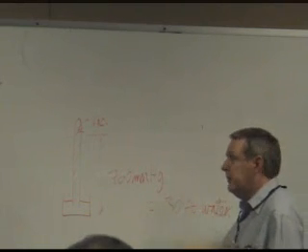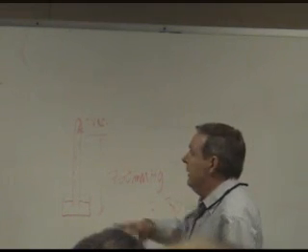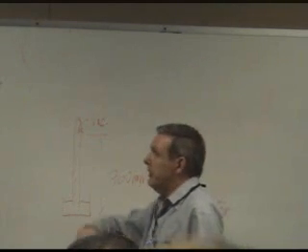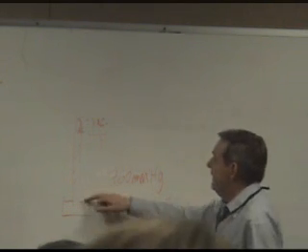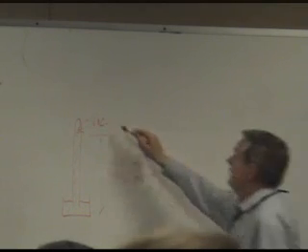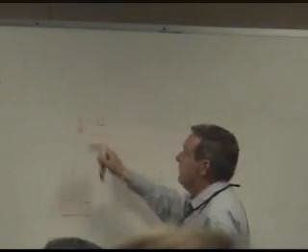So you can sort of see what the problem was here. They had a system where they were bringing in water from the river, and then they bring it up to a high elevation, greater than 30 feet, and then you have a pipe coming down that's open to the atmosphere. So you have a pipe that's open to the atmosphere, just like this, and you have more than 30 feet here. So up here in the exchangers, they were pulling a vacuum. So when they tried to operate this unit, this was the problem. They were having a vacuum in those exchangers, which are right up there.